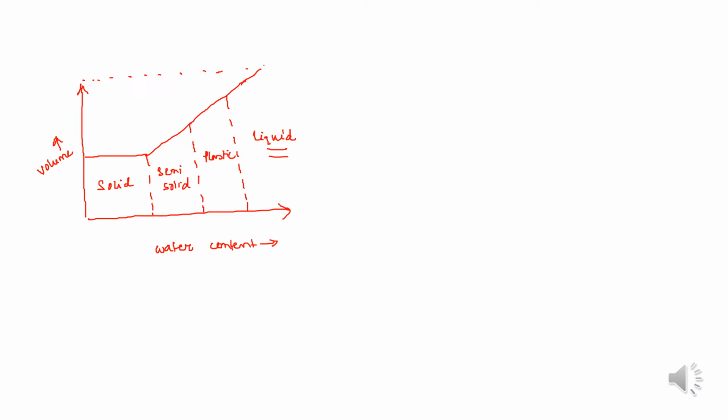Now, when the water content of this suspension is kept on reducing, a stage will come when the soil can be remolded by hand. That means this is a stage when the sample changes from possessing no shear strength at all to having very small shear strength, and that's when we say the soil has reached the plastic state from the liquid state.